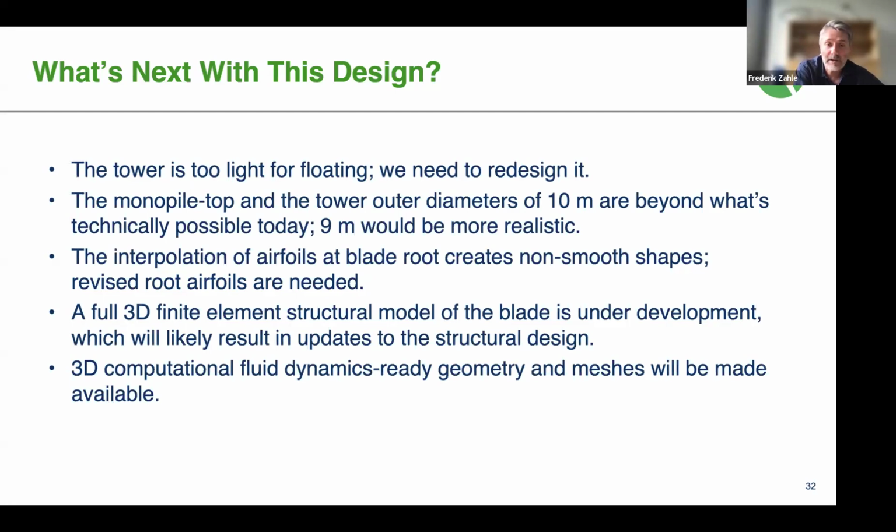In terms of high fidelity modeling, we've also had some feedback, and there will be some work in high fidelity model definition, both with respect to CFD as well as full 3D finite element models that are under development but haven't yet been released. The 3D CFD meshes that were used in the study we presented at Torque will also be made available once we have updated the root design of the blade that right now results in some unwanted non-smooth shapes at the very inner part of the blade.